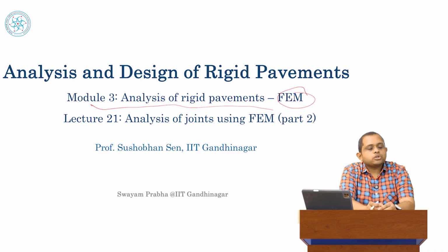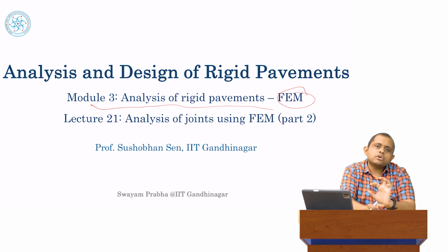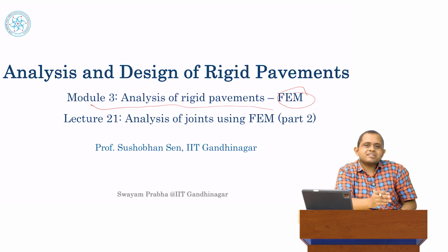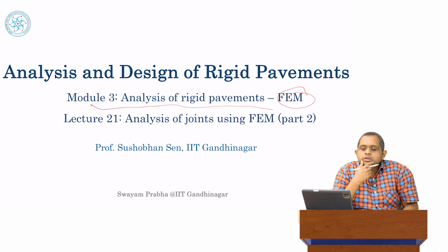In the finite element method, we do not actually start with those same assumptions. So the assumption of a circular load, the assumption of a tensionless spring, the assumption of very large slabs, we don't make these assumptions in the finite element method. Instead, we assume that there is an approximate solution. We assume that our solution is inherently going to have an error in it. And then what we hope is that as the number of these elements increases and becomes very large, the error becomes so small that from an engineering perspective, that is for all practical purposes, the error doesn't matter. So these are the two basic assumptions of the finite element method.